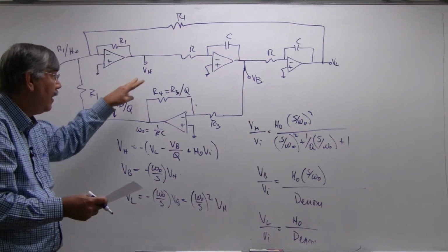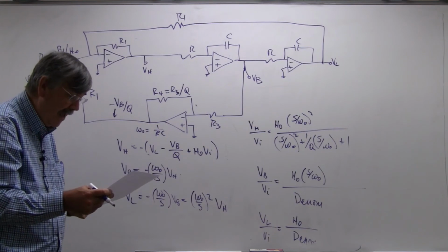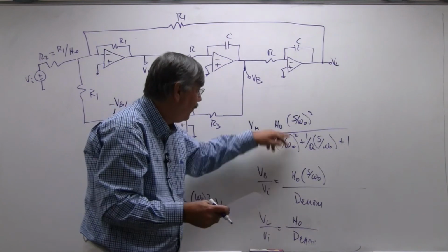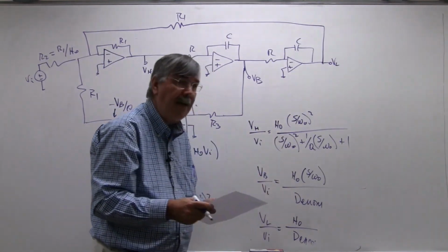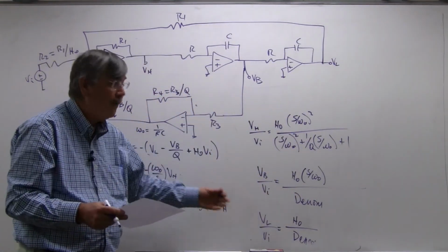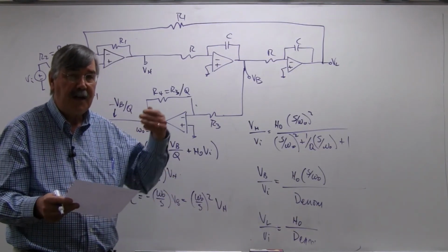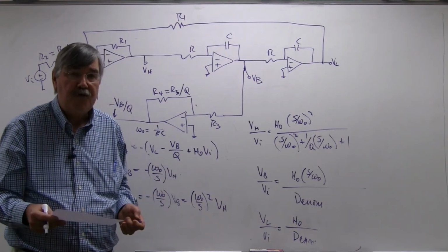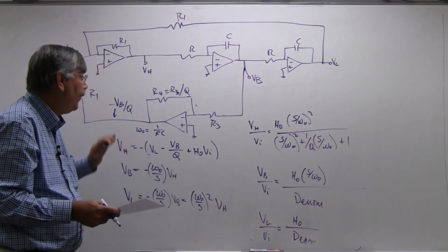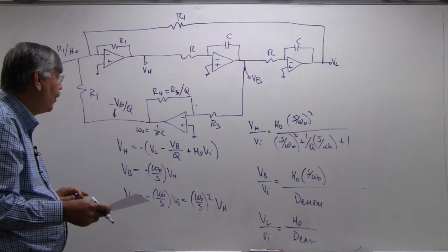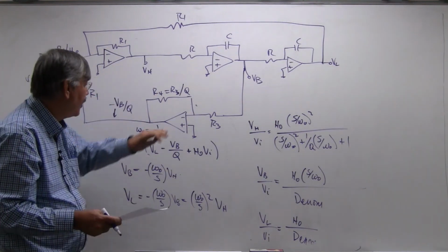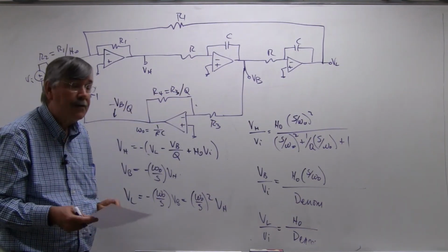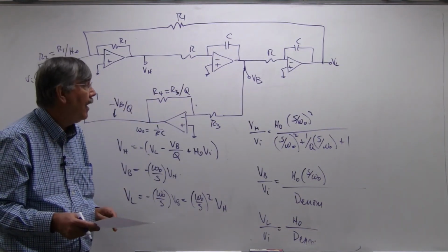And so this really allows you to implement every possible kind of filter. You can use this, again, with another stage to add up some other possibilities. You can implement weighted sums of these things in the numerator and get low pass, band pass, high pass, but also get notch, high pass notch, low pass notch, all pass filters, and probably anything else you wanted. So this is actually a very practical circuit. It works quite well. It has independent adjustment of the center frequency, the Q, and the pass band gain. So we're going to build some of these and have fun with them.